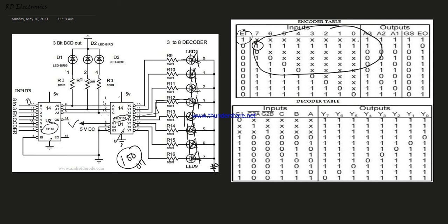Then this is active high, just consider active high. When this is 0, all others are don't care. When this is 1, then all other terms equal 0, that means 0 don't care, 0 don't care, 0 don't care. So that means this is disabled and pin number 6 is enabled, because if we apply 0 on both here, then according to the priority pin number 7 is selected. So depending on the higher priority of 6, we disable this pin. So we should apply 1 here, otherwise the pin is activated.